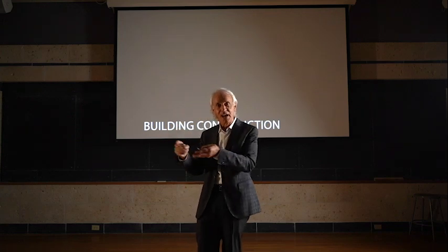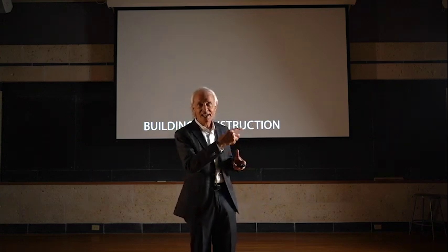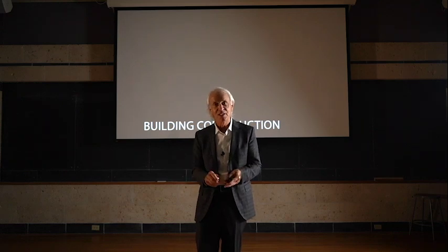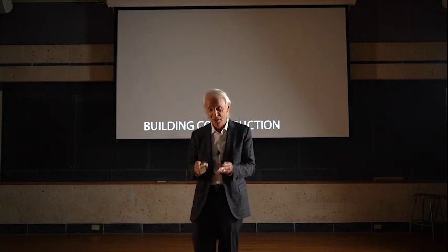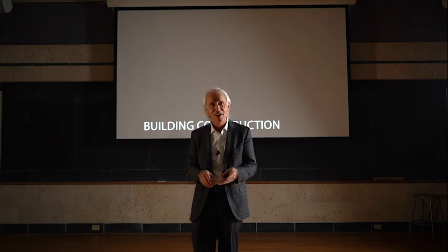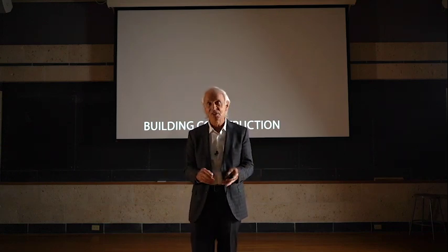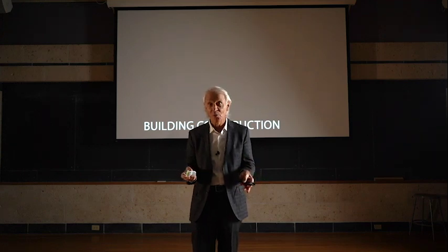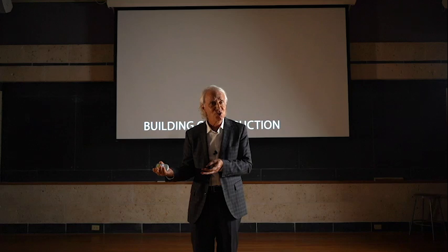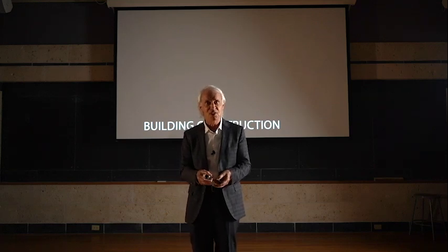You're going to have some factory that's making what are called gang-nailed wooden trusses, and they're prefabricated in a factory somewhere. And those joints are not made with nails, they're made with nailer plates that are put on by a machine. And all of that is much more mechanized. It's able to be done in all kinds of weather because it's in a factory. That is a change in the construction process.